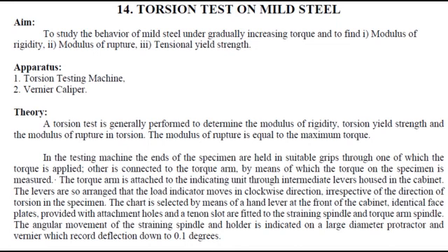Generally, any shafts which are rotating will be subjected to torsion because they are rotating with respect to their axis of rotation. There will be a change in the material deformation. The material will deform in a circular shape, in a circular path. So this is known as torsion. And we have to understand the torsional strength of the specimen or the material, that is, how much load it can withstand when such a twisting load is applied. That we will study in this experiment.